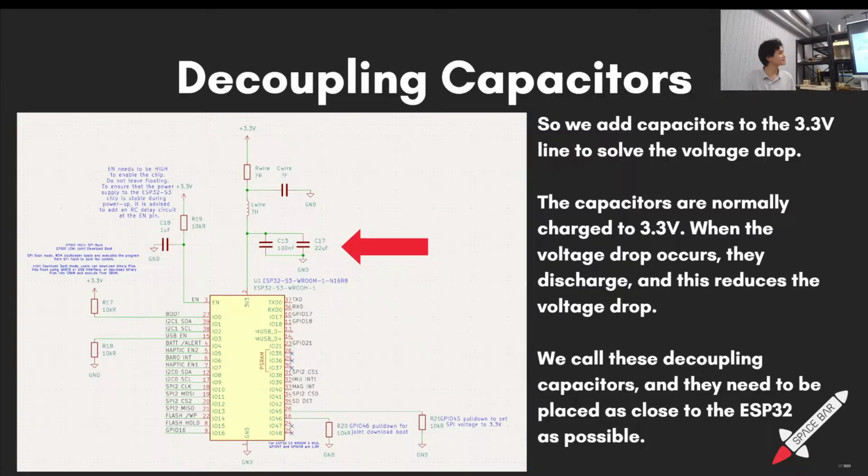So the inductor doesn't actually tank the current, it tanks the voltage. It sees this change in current, and it gets upset, and the way that it manifests this upsetness is by producing a reverse voltage. So across your inductor you will have like minus 0.2 volts, and now your 3.3 is 3.1, you know. But then the current doesn't get affected, right? Oh, it does.